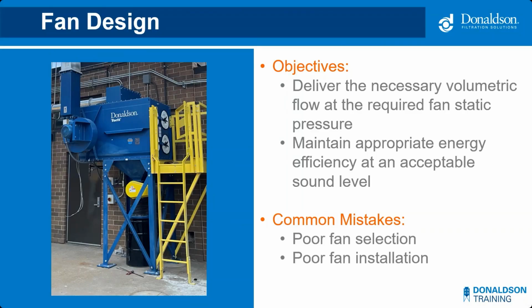First, the fan must deliver the necessary volumetric flow at the required static pressure to drive operation of the system. And since many dust collectors can operate with clean or dirty filters, the required airflow often has to be maintained over a range of static pressures.